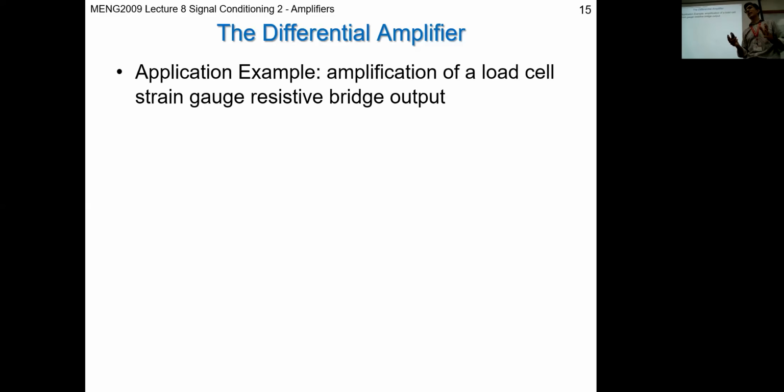So you apply strain gauges, two that are basically in line with the direction of the load that will actually compress, and the resistance will reduce, and two that are perpendicular to the orientation of the load, and by Poisson's law, they'll actually be in positive strain.